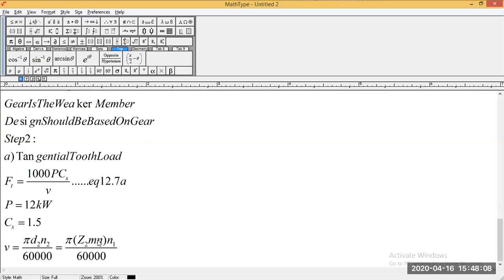We're finding the normal module. This is for the spur gear, right? So always designate as MN. This formula is not given in the data handbook, so you need to make this small change here. So don't find M, find MN, because in the next stage you should not get confused. The part 2 of this step now should not get confused. So designate this as MN. This is only for helical. You need to make this accommodation.